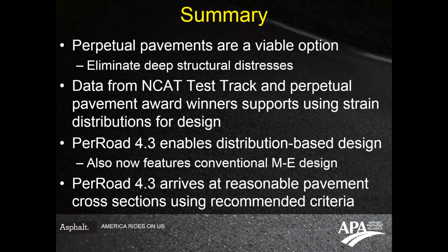Data from the NCAT test track, and from real world pavement sections, support using a strain distribution for design. You can now do that within the PerRoad software. It's been validated and it's now fully functional. You can also do conventional ME design within the software.